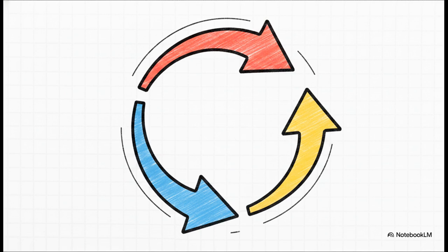If we were to swap just two of those phases, the order completely changes to what we call a negative phase sequence. Instead of red, yellow, blue, the peaks now happen in the order of red, then blue, then yellow, RBY. So this creates an anti-clockwise sequence. And just like before, BYR or YRB would represent this exact same reversed cycle.